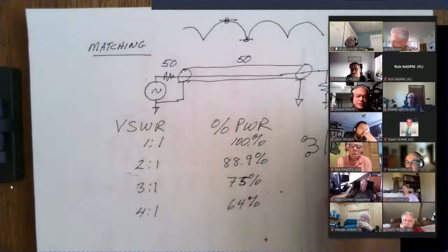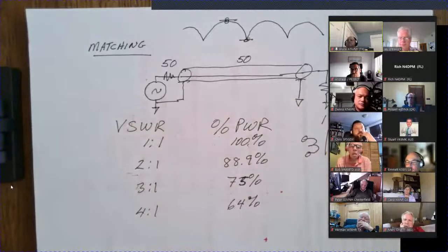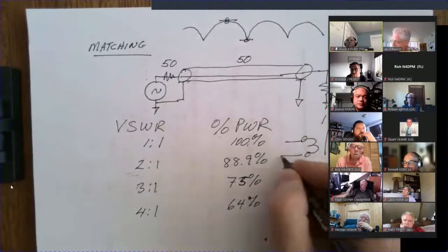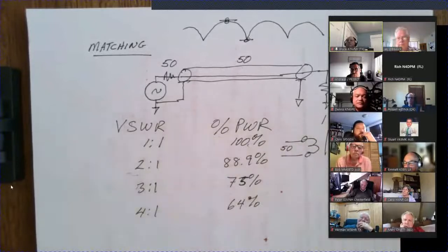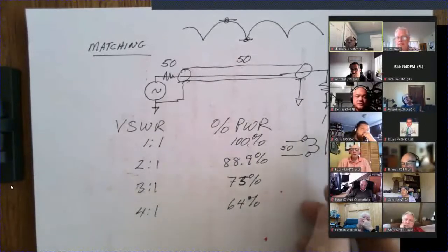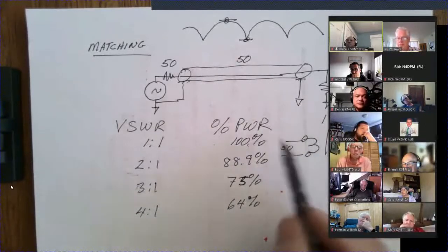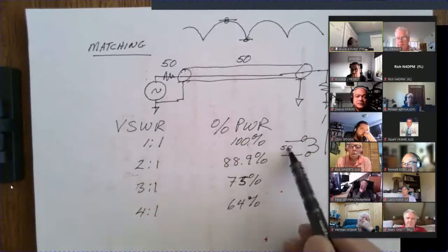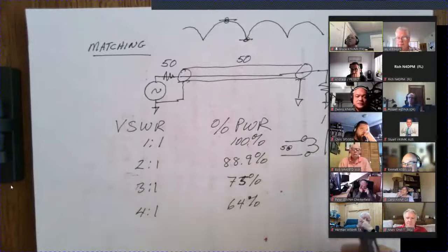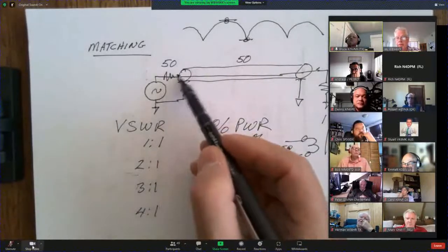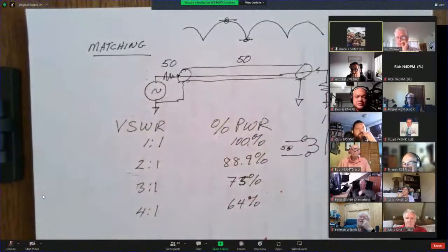There is a ratio of impedances of 4-to-1. So on this side, we could have 200 ohms, and on this side, it would look like 50. You'd have some heating in the transformer, some loss, but it would certainly not be what you would have if you tried to match 200 to 50 ohms directly. So a balun here would help, not here. A balun at your antenna would help. Okay?